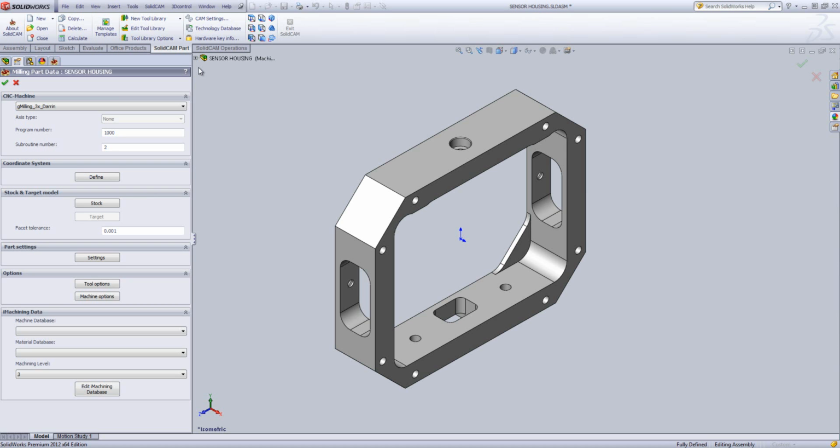If your system is set up for manual mode and revisions are made, you will see the familiar SolidWorks red and green stoplight icon on top of any toolpath that was affected by that particular revision. You may also see the icon over the stock or the target if they require synchronization. Provided the SolidCAM settings are correct, the design model will notify you if changes are made to the SolidWorks file. If you want the design model to affect the SolidWorks model, this would require you to copy the design model out of the CAM folder, rename it to the original SolidWorks file, and overwrite the original SolidWorks file.